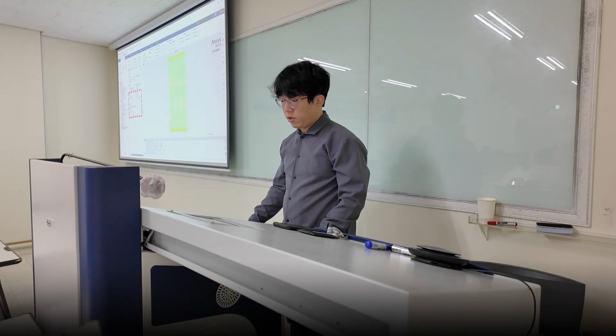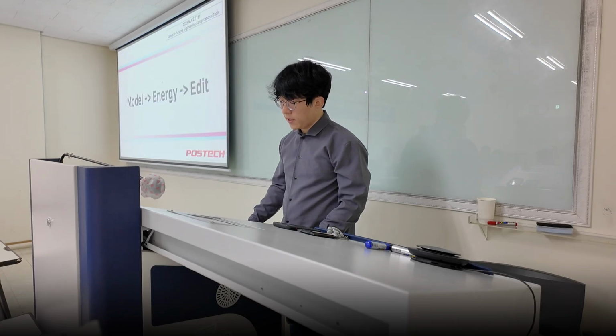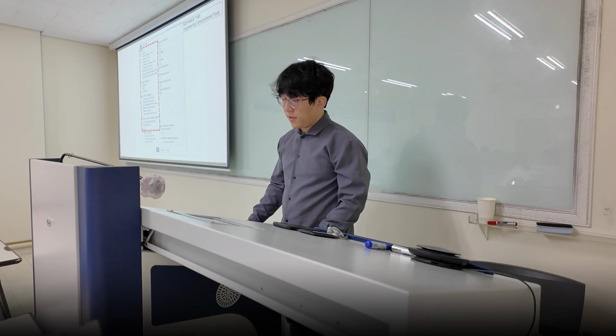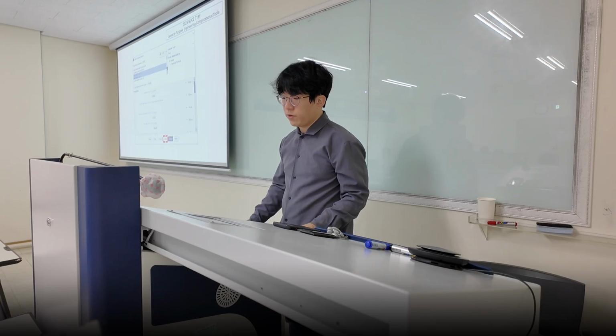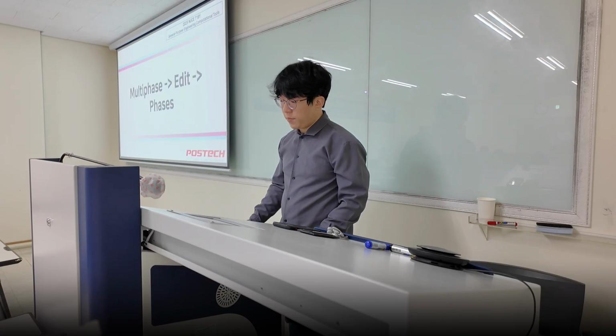You're going to load it to Fluent, and then create a 2D space for planar analysis. This time you're going to add the energy equation, and then set up the turbulence model. Also include thermal effects. This time we're going to have phase change, so we're also going to include two fluid materials for liquid and gas, and we're going to have a copper surface at the bottom.